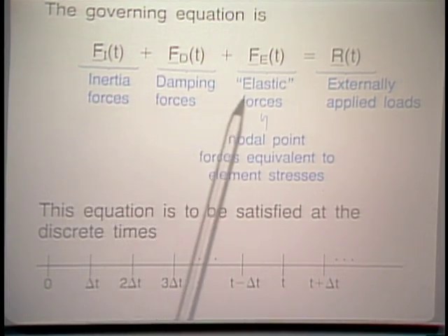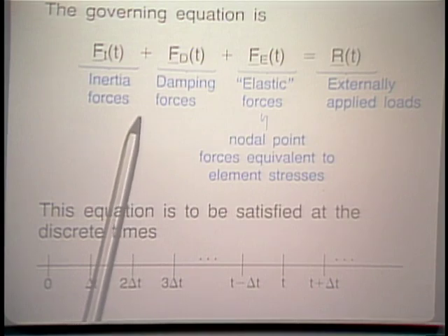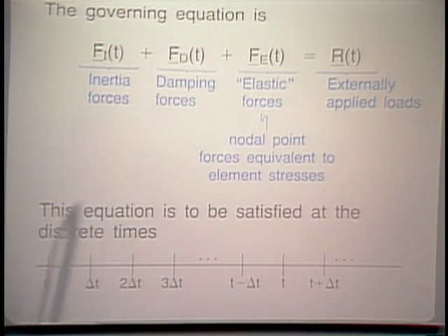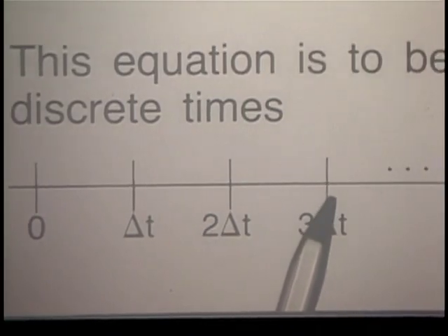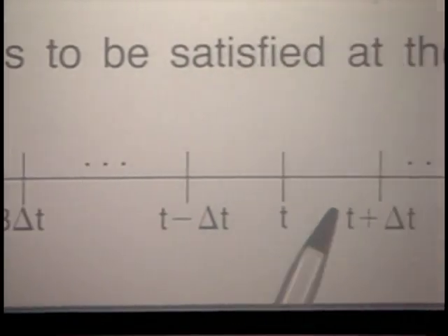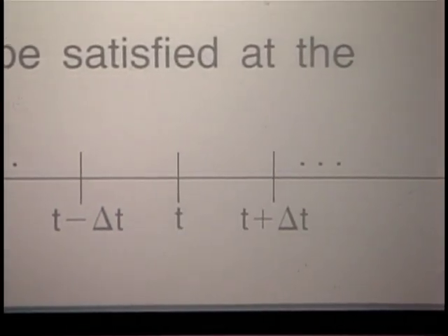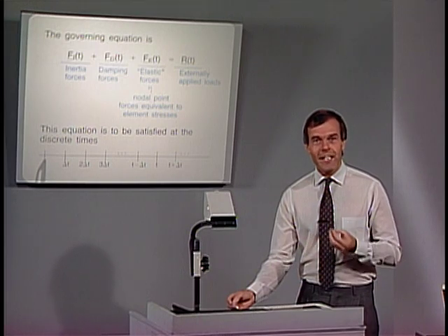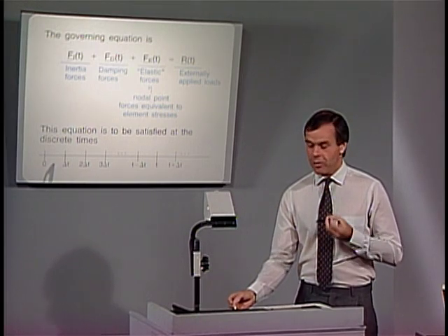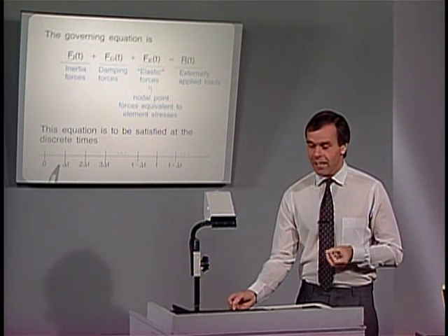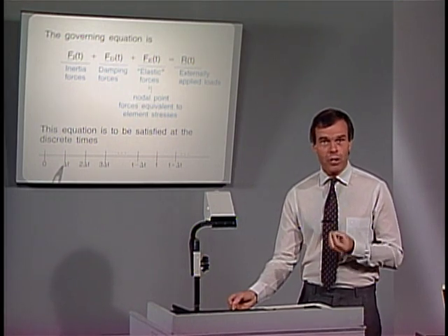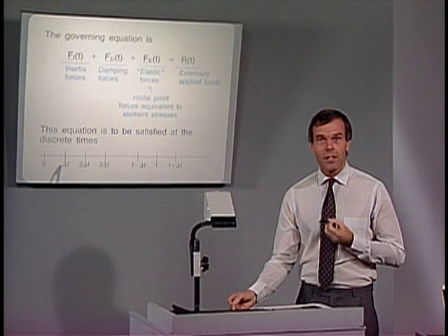This set of equations should hold at any time t during the response solution, and in direct integration analysis we consider this set of equations at the discrete time points delta t apart, as shown down here. Of course, even in static analysis we always worked with the delta t time increment, but in static analysis we did not include the inertia forces and the damping forces in the analysis.